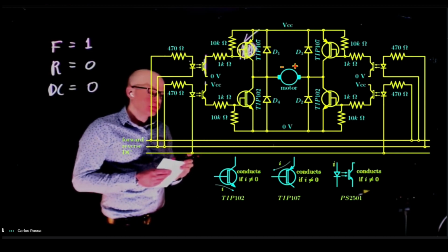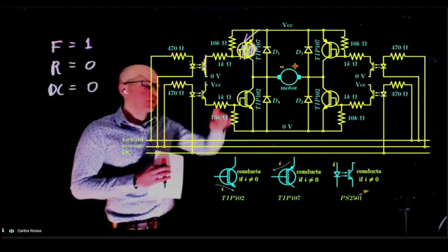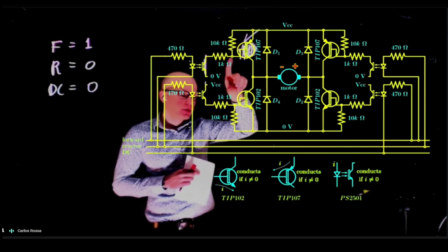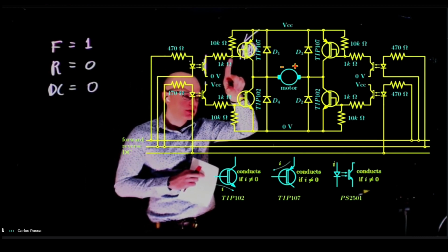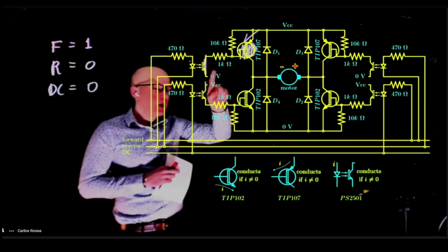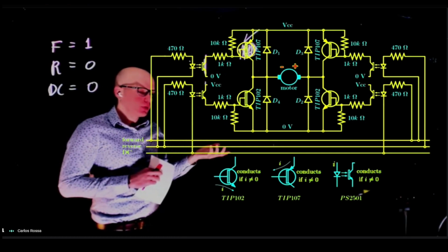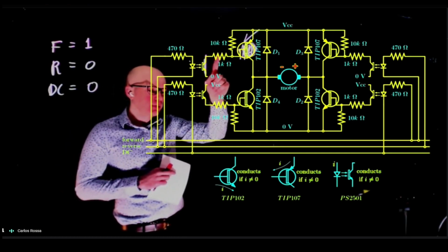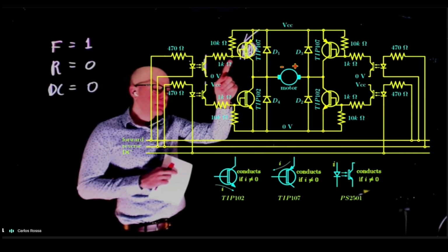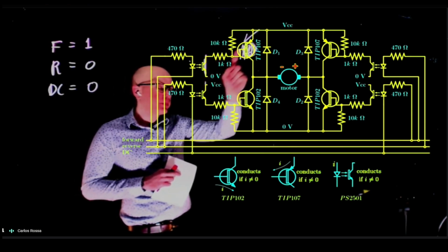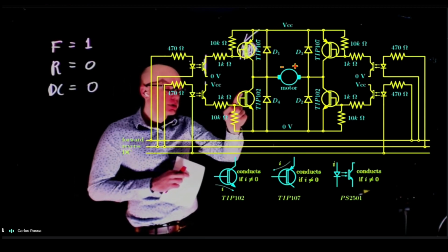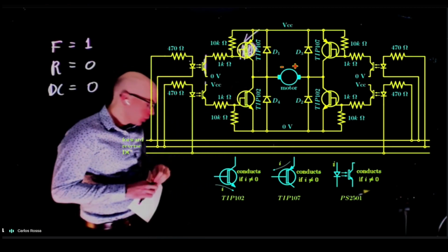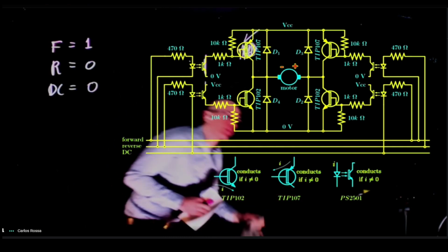Yes, of course, there will be a potential drop here and a potential drop there. But the potential drop here is a lot smaller because of the resistance. Oh, I see. Well, actually, no. We can't just connect that to the ground, to 0. Right. We need this 1 kilo ohm there. Because otherwise, if you didn't have this 1 kilo ohm, then you would go from VCC straight to ground, and you would short the power input. Right. Okay, that makes sense.